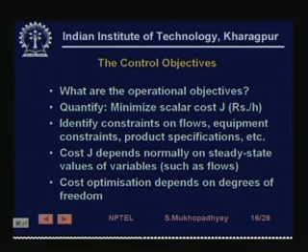Now, this cost optimization, to what extent it is possible, depends on the degrees of freedom. Now, what are the degrees of freedom? It tries to answer this question: suppose you say, okay, this is the plant, these are the governing equations, these are the things which can be manipulated, and those are the things which cannot be manipulated, they are given to us, they are disturbances, some feed coming at some flow rate or some temperature, with no control on that.